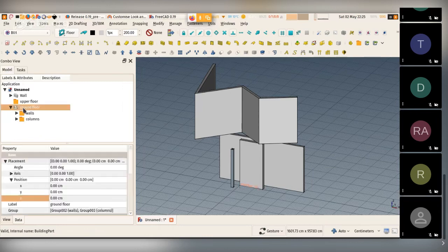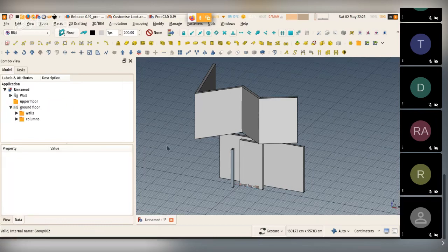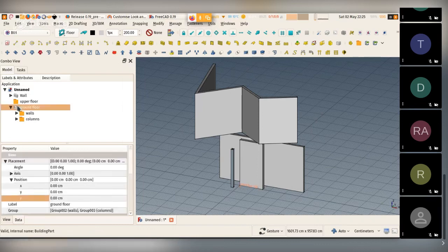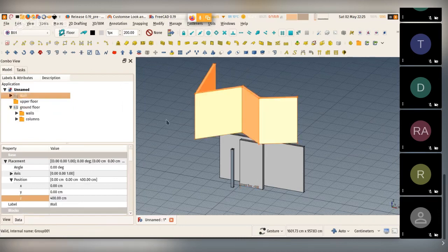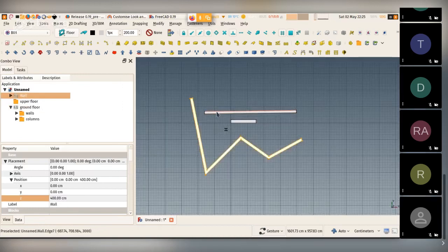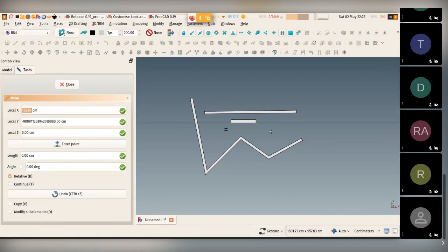And these levels are not only levels; they are just any group of objects that you want. So you could use this not only to represent levels, which is the most usual way we use them, but also to do stuff like components, reusable components. They are clonable as well. We don't have in FreeCAD the concept of family like you have in Revit. What you do is determine that you have one element like this, and you just clone it.